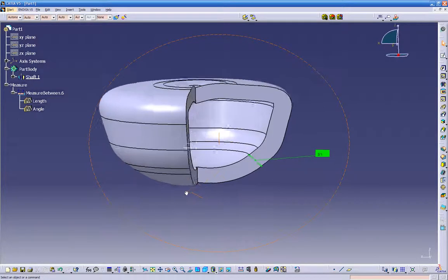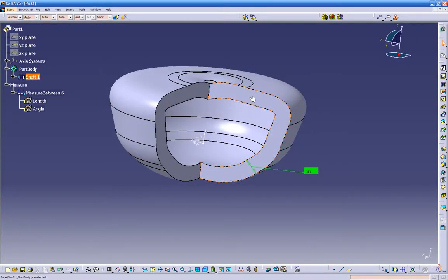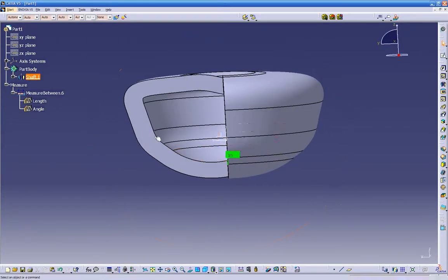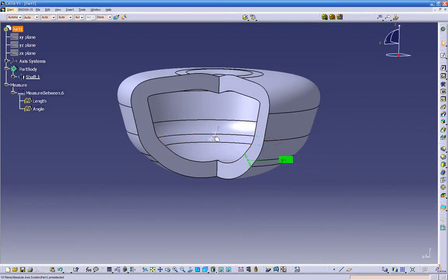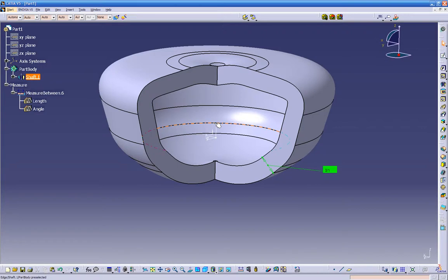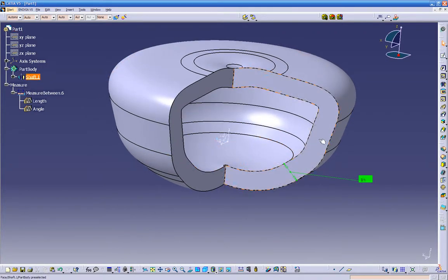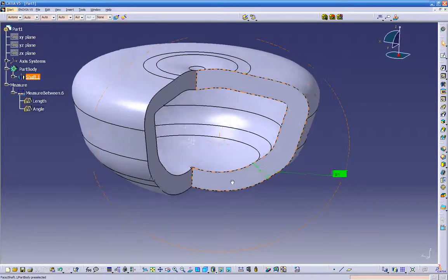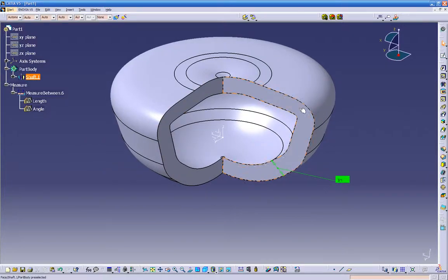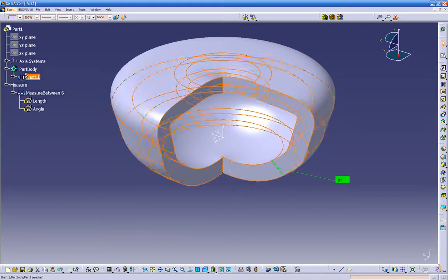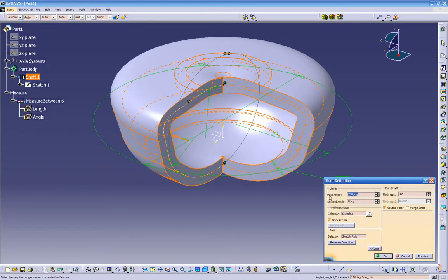let's try to build now a sketch on this surface over here, or we can build it on the plane, because right now, as you see, our plane is in the center. So it can go either on the XY or XZ plane, we can create a sketch right now, or we can create a sketch on this plane. We can do either or. Let's go a little bit more advanced this time. So instead of going on the regular, let's change its angle to an odd number, 223.